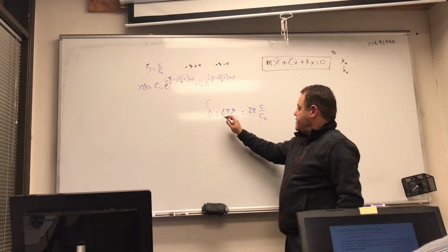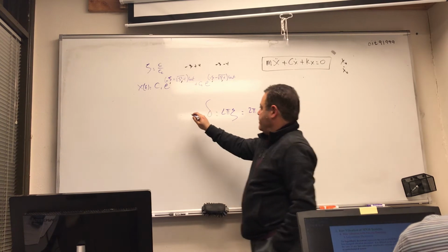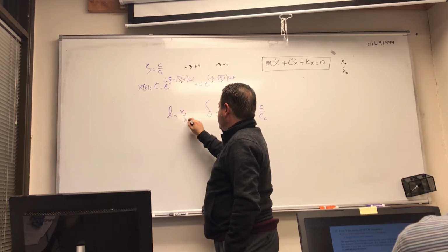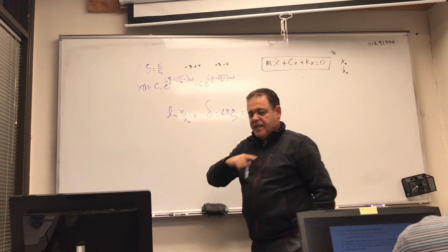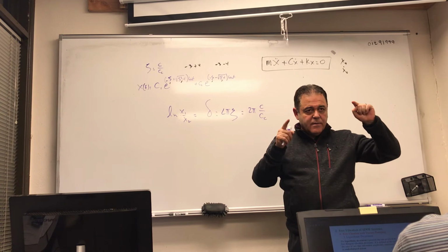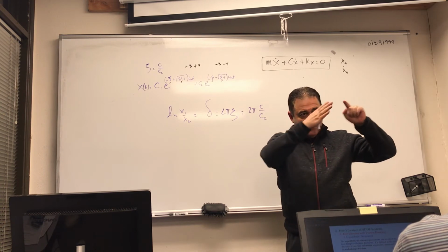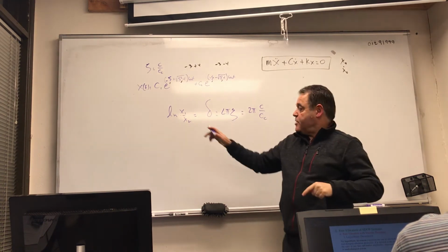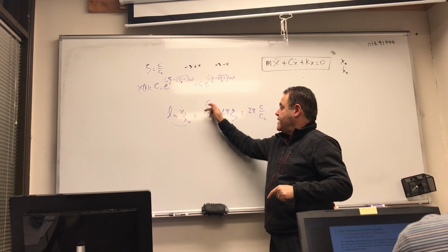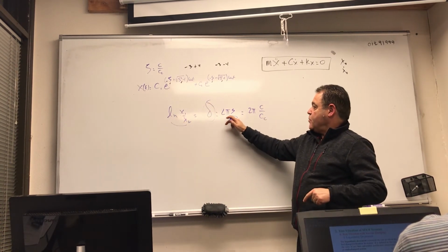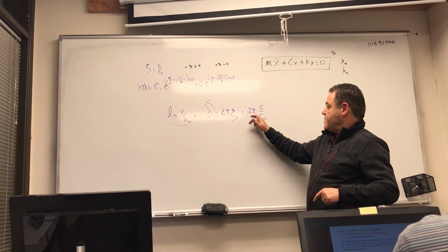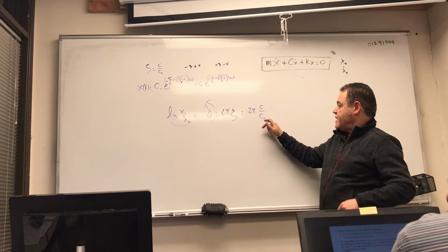If you measure the logarithmic decrement, which is the log of x1 divided by x2, you do an experiment, and between two cycles of vibration, you measure x1, you measure x2, you take the log of that, you find delta, then you say it's equal to 2 pi zeta, but 2 pi zeta is equal to 2 pi c over cc.